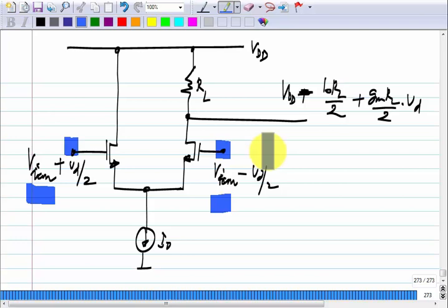Right now, you can include it if you want, it won't change anything of the analysis that we are doing, but you can think of VICM as only the bias voltage that you set, lowercase VCM as any common increment to the two sides, and lowercase VD as the differential increment between the two sides. Okay. But that lowercase VCM could be thought of as simply modifying the value of VICM, it is the same thing.